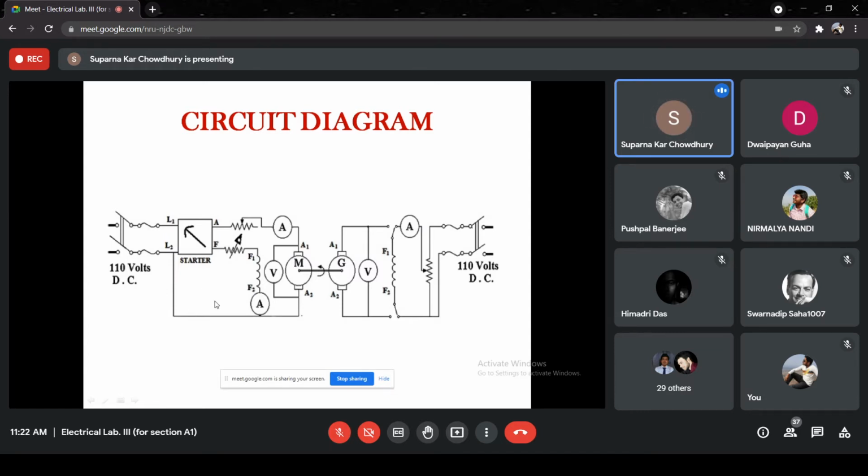It should be noted that for each and every set, the various speeds should be constant. That is, for the initial run, when the motor was uncoupled, we took readings for say 100 rpm, 200, 300, 400, 500, etc. Then for all the subsequent runs, we should have readings for the same speeds, because unless we keep the speeds the same, we cannot separate out the motor losses.